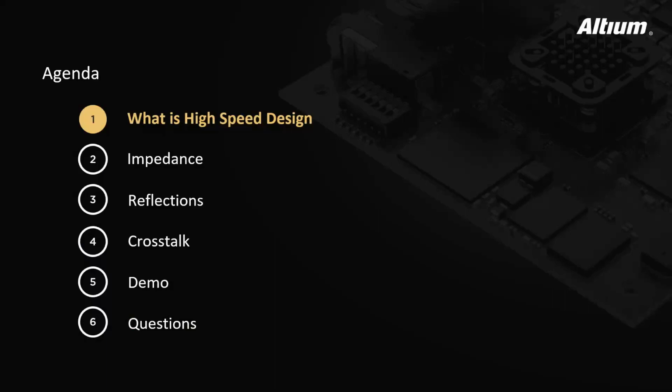And we will see how to define a layer stackup and set up impedance profiles. Then we are going to use these settings to simulate signal integrity and crosstalk.